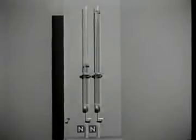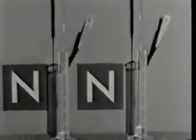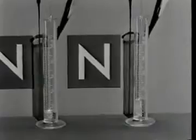The basic phenomenon occurring here is more easily seen if the pressure head remains practically constant. These are two identical burettes containing the same Newtonian fluid. The pressure head in one is twice that in the other. The ratio of rates of flow is also 2 to 1, as we expect from Poiseuille's law.